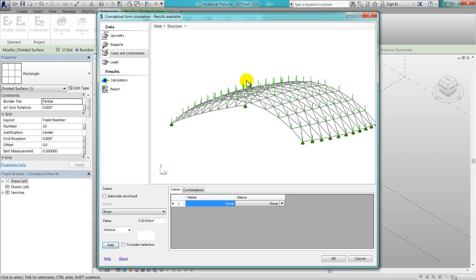Notice that little downwards pointing arrows appear. They are resembling the area load. The program automatically creates concentrated point loads on the mesh nodes according to the value we put in here.